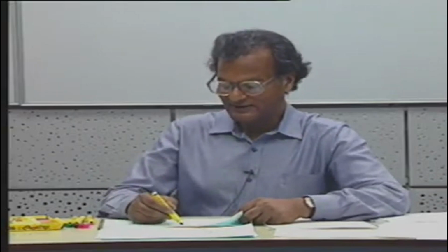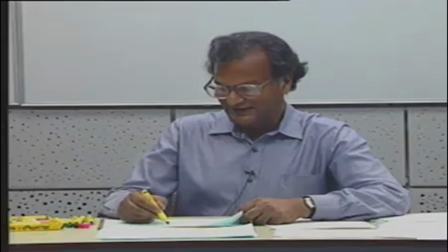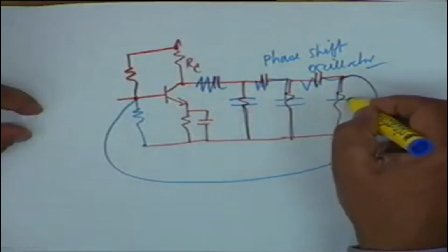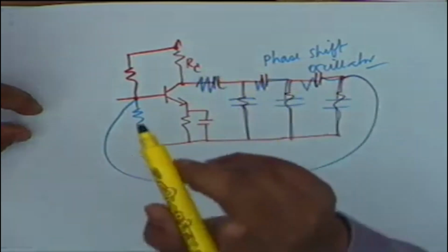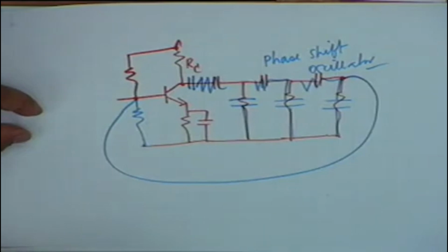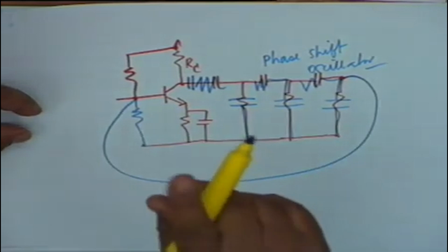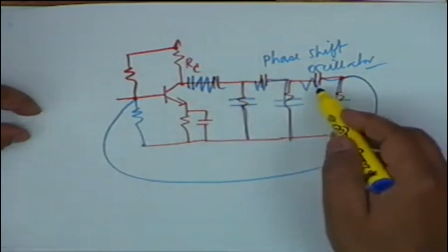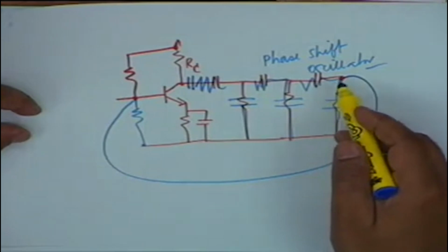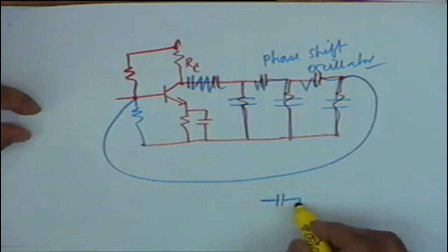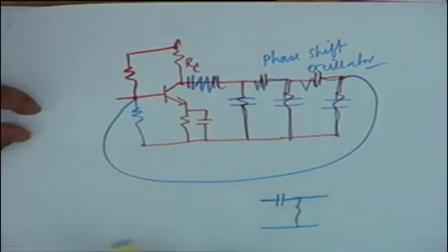If that satisfies Aditya, what we shall do is we will use an R here and a C here. It gives the same result, except that we require an extra capacitor here. Isn't that right? Because otherwise you cannot block out DC. That is why the CR circuit is preferred. This would be a lead circuit, pi, 180 degrees leading, isn't that right? Because in the CR circuit, the output is leading the input.